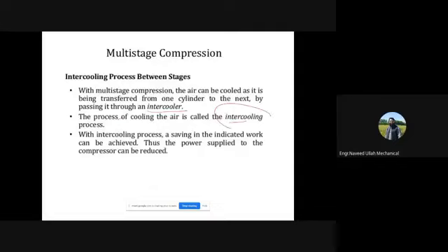With intercooling, the process will be nearly equal to PV equal to constant. We have studied that with intercooling the process will tend toward PV equal to constant, and with this type of compression, as we discussed previously, the work consumed will be less. Make sure you understand this.